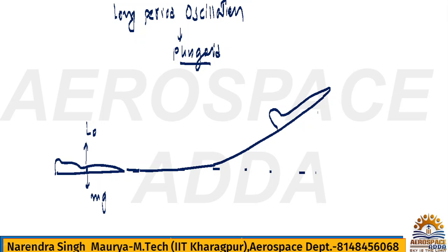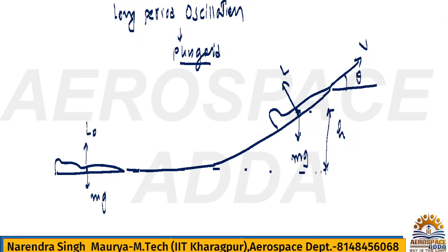So now this airplane has gained altitude. You just say for this airplane, from the horizontal reference, this altitude is nothing but h, and obviously now the velocity will be v here. Perpendicular to velocity we have lift L now, and that weight will be continuously working downside, mg downside. And we have a flight path angle from the horizontal reference. Flight path angle is what? Theta. Remember, theta is the flight path angle, it's not an angle of attack. That discussion we already have done in last lecture.